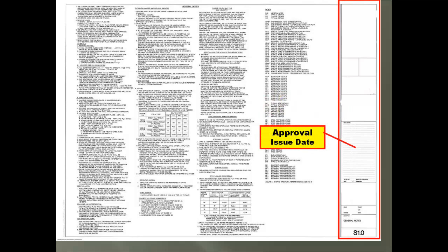Here in this box would be the list of delta or change order numbers and their dates of approval. This is a critical location to check if things are not lining up with what you are looking at in the field or shop against the drawings, because you just might not have the latest approved set of plans.